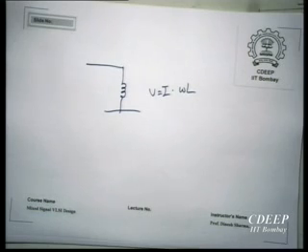In fact, we go back and say, oh, that is why our beta multiplier was working so well. It had no business being so good. At that time we were just too busy celebrating. But the reason why it is so good is, apart from doing everything else that we had talked about, it had also transformed the capacitive input impedance into an inductance in a load, and that was a natural high pass, and that was compensating, and therefore it was even better than what we had thought.